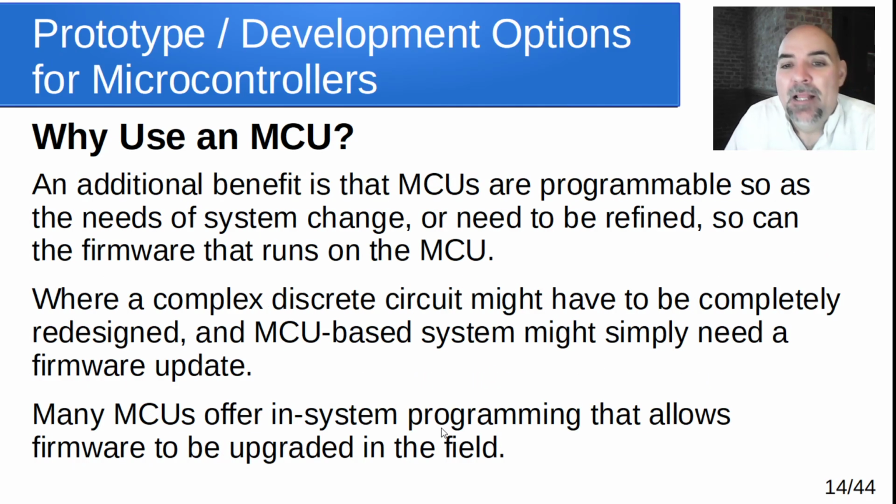Now, one of the other things that's useful about microcontroller-based systems as opposed to discrete circuit systems is that since they're programmable, you can actually change the program and make it do something different. And there can be a lot of advantages to that. One would be you could have different levels of your product. In other words, you could have a product that has simple features. That's a different program than one that has the professional version or more complex features. So you could use the same microcontroller in a family of your products that you're designing and just put different programming on them.